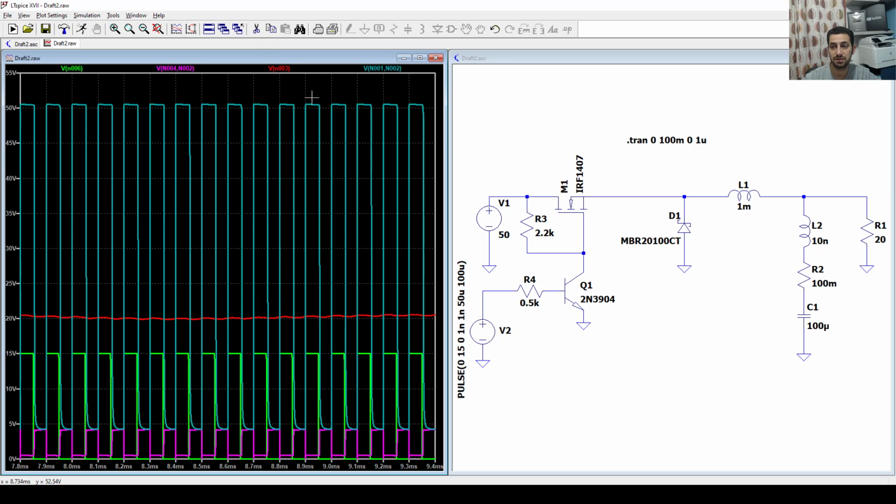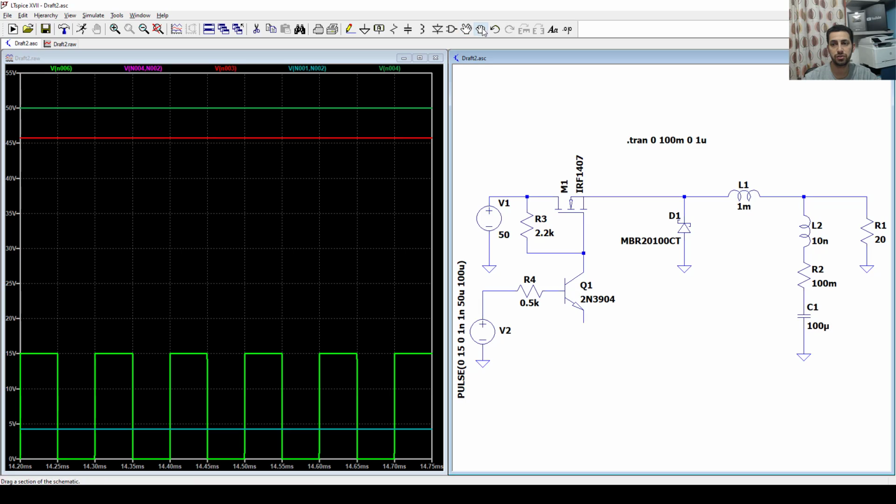So that's why it's not good to have a higher voltage drop across my transistor, because that voltage drop will be applied across the resistive RDS(on). V squared divided by RDS(on) will produce high thermal stress. The different solution is to make a push-pull configuration, where we have not just one transistor.